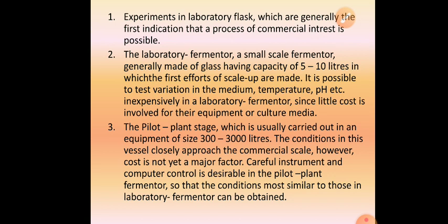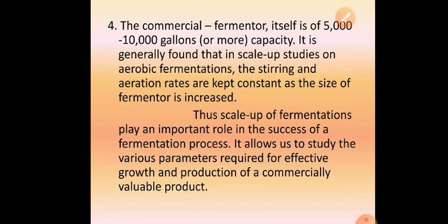Careful instrument selection and computer control are desirable in the pilot plant fermenter so that conditions most similar to those in a commercial fermenter can be obtained. So after lab fermenter, you transfer the process to a pilot plant stage having a capacity of 300 to 3000 liters and study the process in detail. And then you transfer the process to a commercial large scale fermenter having a capacity of 5 to 10,000 gallons or even much more capacity.